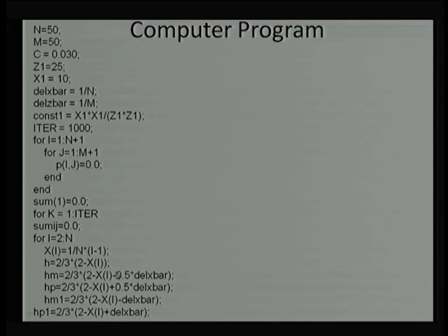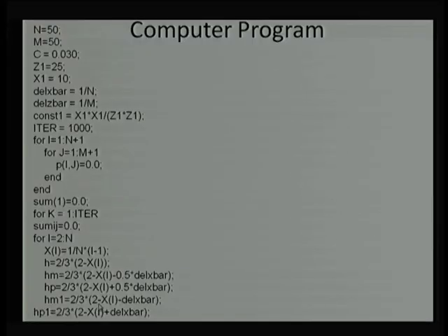Otherwise, in this case in every iteration this will be calculated again, which is important when we are calculating the elastic deformation with variation in the film thickness because of the pressure. Otherwise, higher pressure variation is not going to cause any change in the film thickness. That is why we should not use it here, but just for commonality we are maintaining it over here.